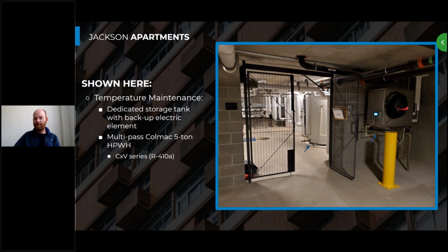If we ducted the exhaust from this fan out of the room like we did for those two primary heat pump water heaters, we'd have to come up with some solution to disconnect that ducting to open this face so that someone can service the interior components of that heat pump water heater. So we knew that this one uses 410A, it can work down at cooler temperatures, so we're not as concerned about those low ambient air conditions.